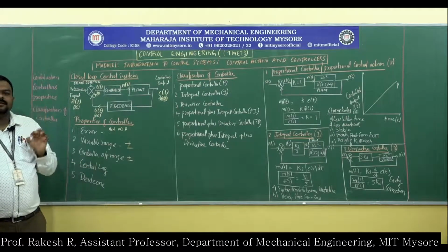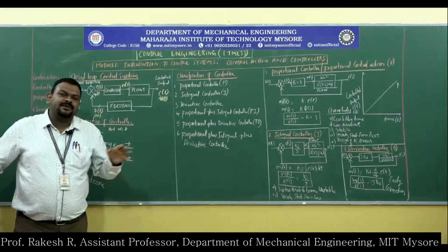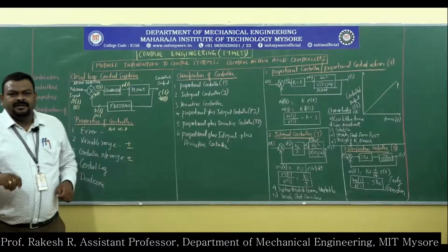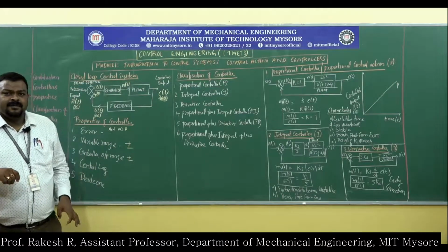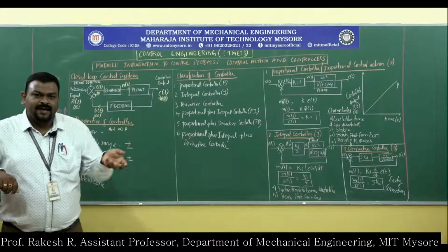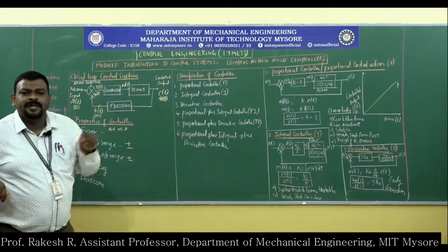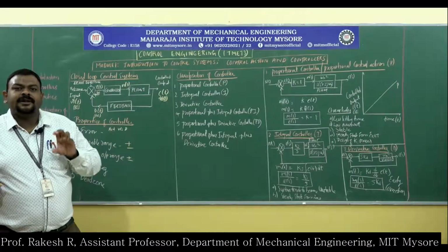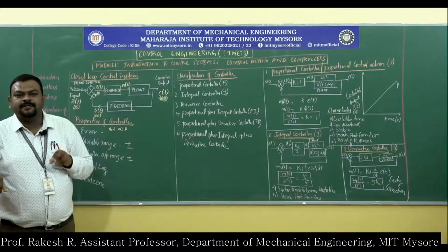In some cases, control lag is essential. In some cases, control lag is not essential. In some cases, control lag may be a threat. Whenever we want to open a fluid valve, in such cases we need to give some control lag, because sudden opening of the valve can increase or decrease the pressure.